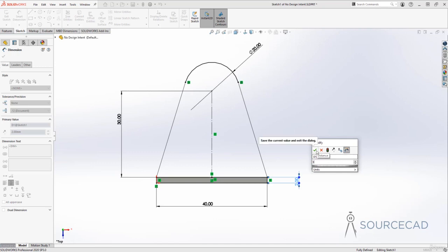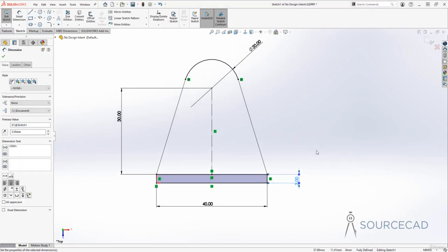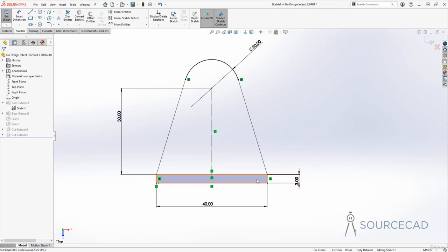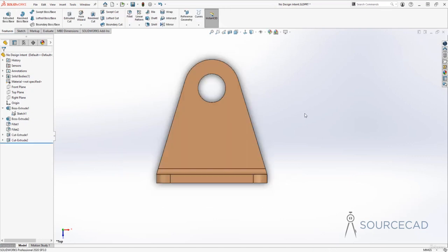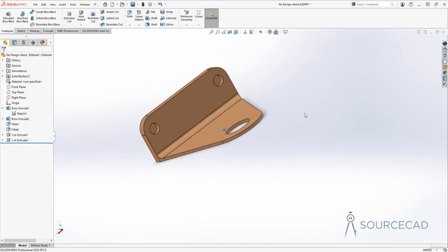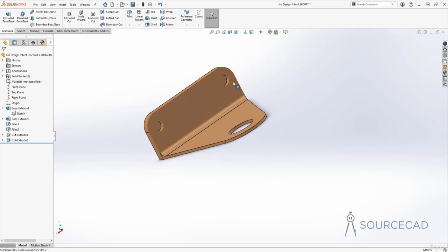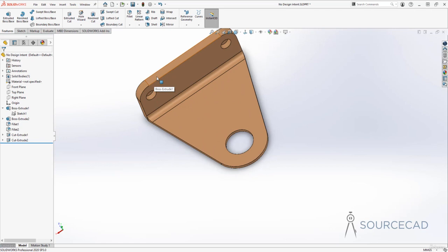And I'll click on this green tick mark. So it is now changed. Now we have this thickness as 3 unit. So we are done. Let's click on exit. All right, and let me orbit this drawing and you'll see this. Now we no longer have these two holes. And why is that? Well, that's because the thickness has increased and the hole depth is just 2 unit. It's just 2 mm. But now this object has a total thickness of 3 unit or 3 mm. And that's why we no longer have that hole.